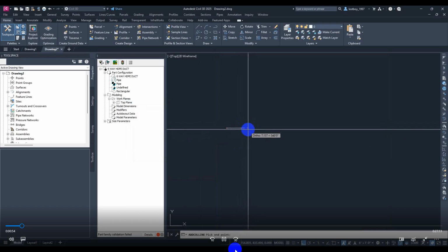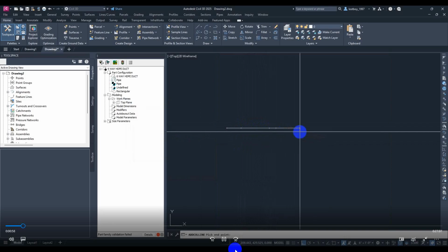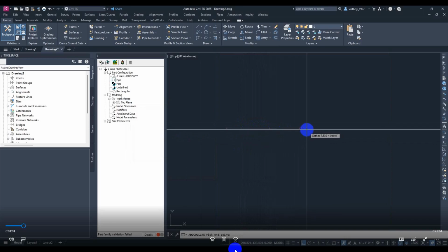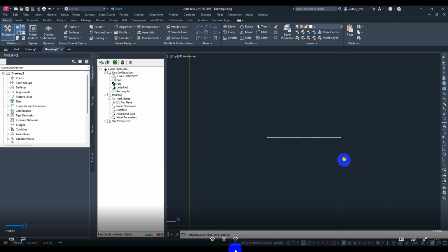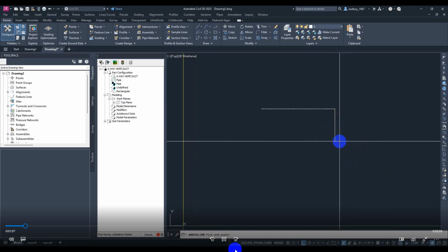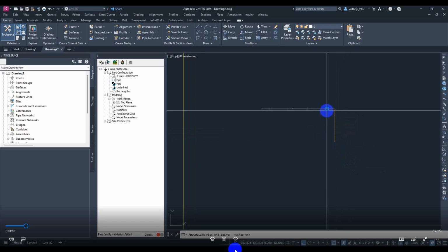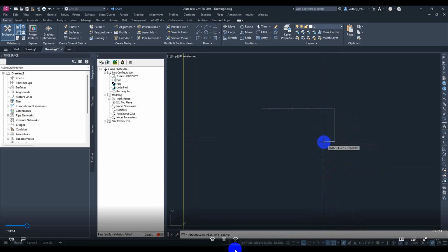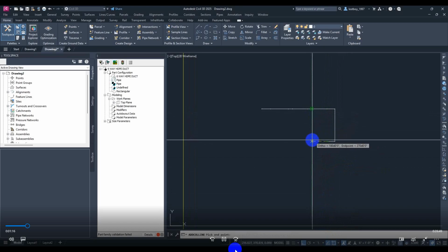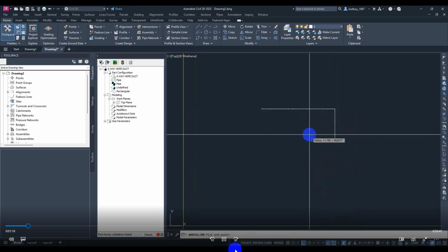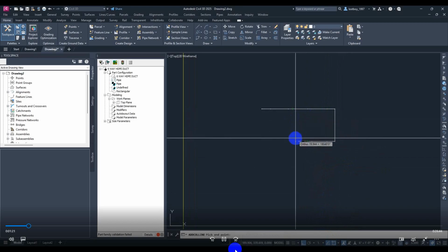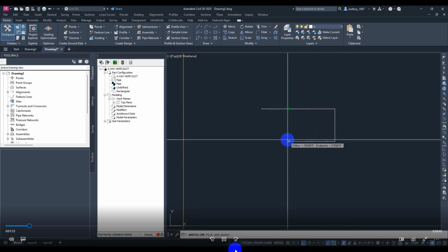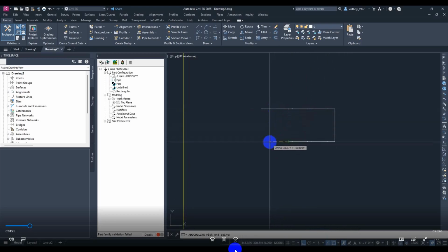So we will be adding some points. These points later will represent the arcs or the circle of the HDPE duct, as we will see later. When you are doing this, you have to make sure that these points align together by activating object snap and tracking. You have to make sure that they are located vertically on the same line, as I'm doing now.